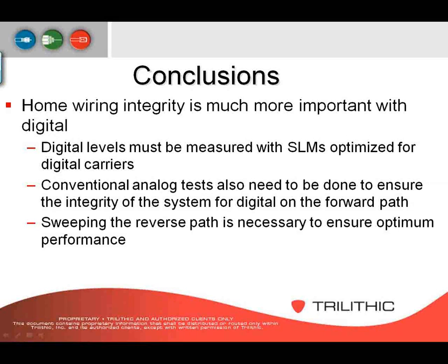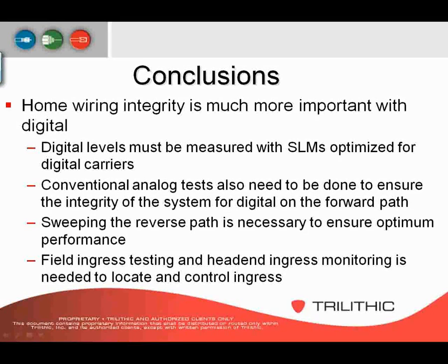Sweeping the reverse path is necessary to ensure optimum performance. The thing is that return is an area where a lot of distortion will gather. So you want to make sure that return stays nice and clean. If you can keep that clean, you'll also notice improvements on your forward. Field ingress testing and head-end ingress monitoring is definitely needed to locate and control ingress, because you want to be able to identify problems before the customer has to call. Remember, you want to be proactive, not reactive.